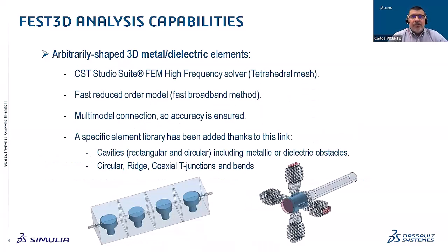In order to extend this, because as I said, this is working fine for metallic cavities, we have included a finite element solver into FEST3D. And the way we have done this has been by the integration of the high frequency domain solver of CST Studio Suite. In this case, we use the fast reduced order model implementation, which allows, again, fast broadband calculations. And the connection with the rest of the circuit is done through a multimodal connection, ensuring, of course, accuracy, if enough modes are taken into account.